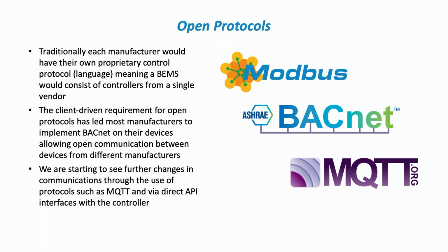But there is a kind of adversarial element to BACnet where engineers like me love it. IT engineers, because of the security side of it, are not quite so keen on it. So you have to implement security. But it is an open protocol. Anybody can implement BACnet on their system.